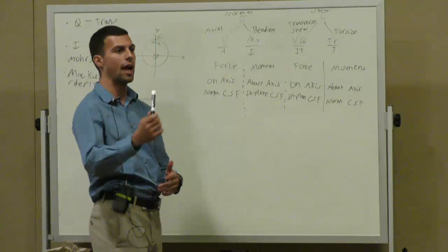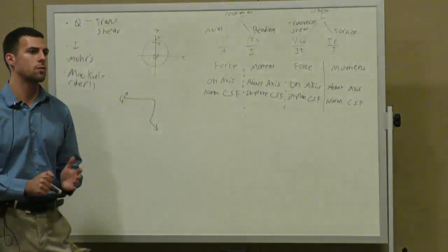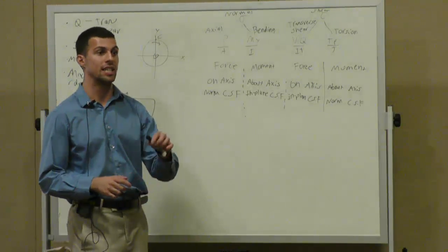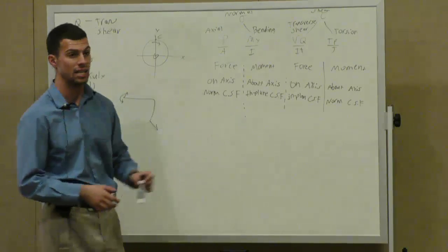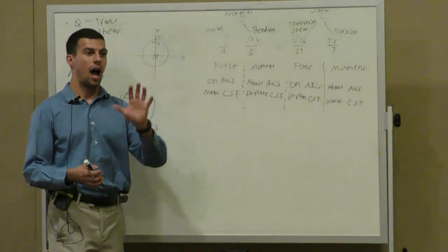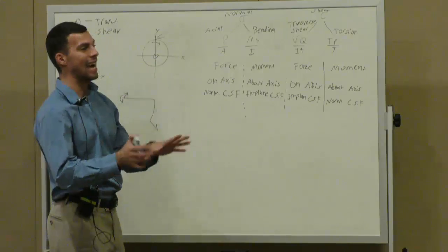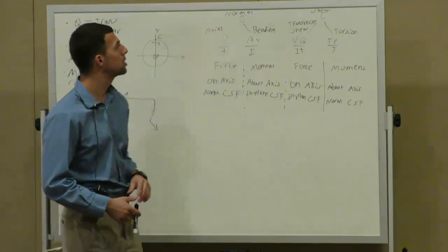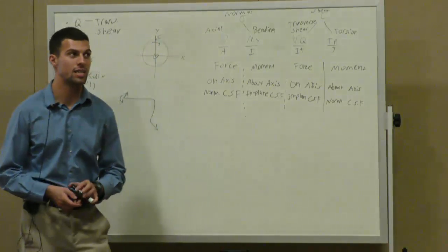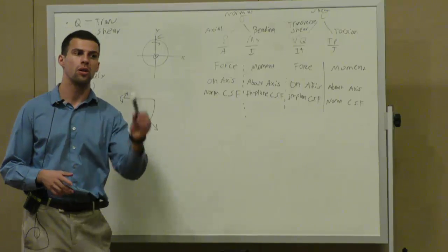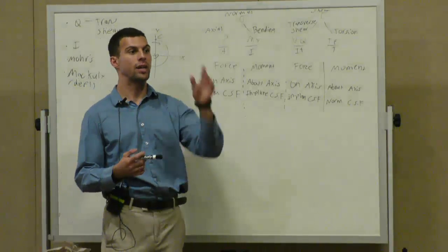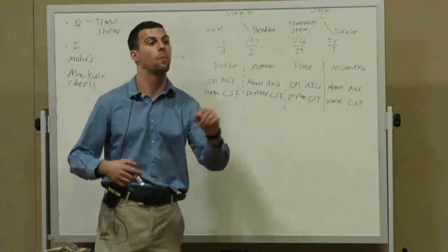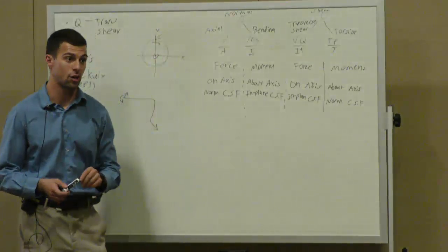We usually approach statically indeterminate things from the perspective of deformation rather than from stress. So I don't want to say definitively you can use superposition of stress to solve for statically indeterminate. You can use superposition of deformation to solve for statically indeterminate.